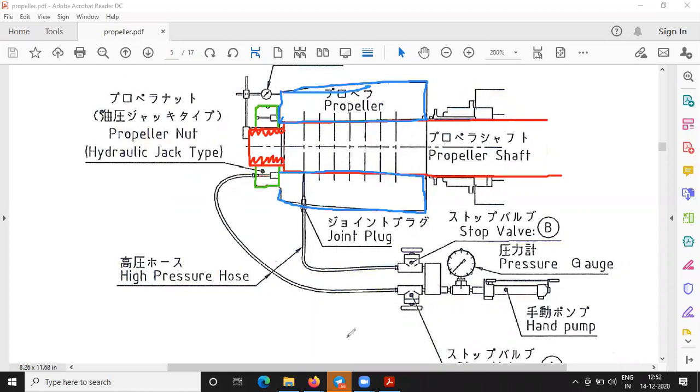Now you see this is the oil pressure which is being given onto the shaft, so that the oil transfers here on the surface of the shaft and starts expanding the propeller bore, and a frictionless surface forms in between the shaft and the propeller. Okay, this is what we call wet pressure. That is the meaning of wet. This we call the wet pressure, and this one we call the push-up pressure.